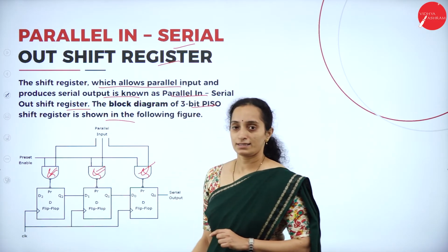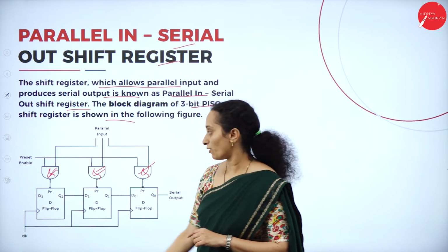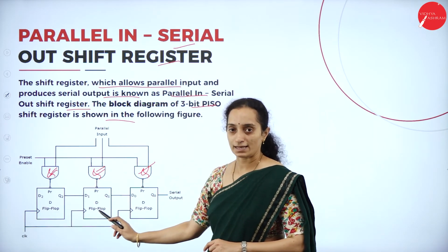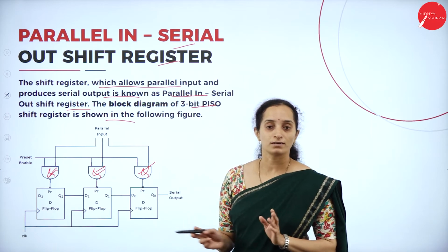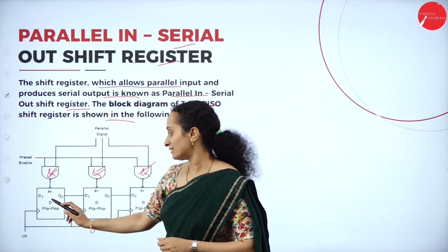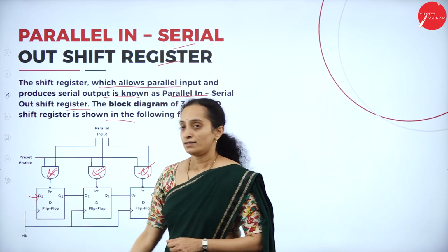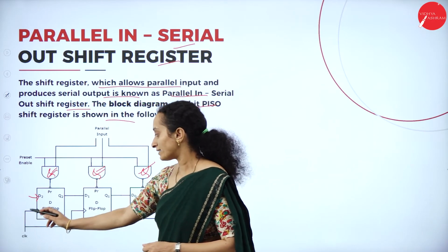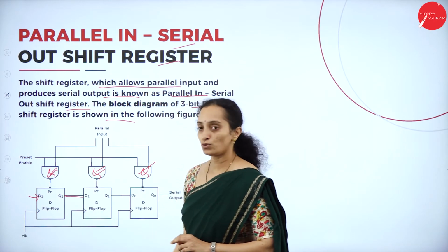It uses three parallel AND gates to provide one of the inputs to the flip-flop. One AND gate provides the input to one flip-flop, the second one to the second flip-flop, and the third to the third flip-flop. Along with the value from the AND gate, we are also getting the input from another input way. We are getting two inputs and a clock pulse for the D flip-flop. It produces Q2.